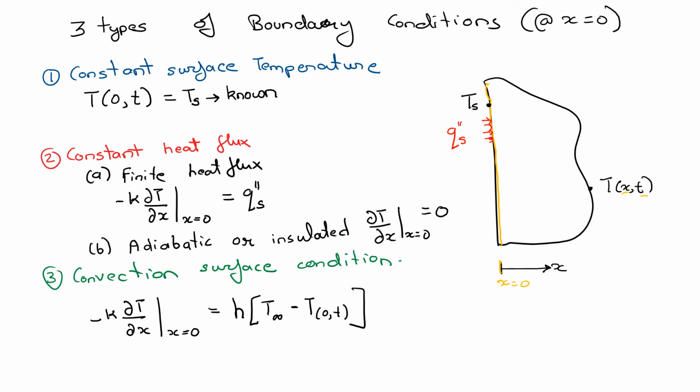In this case, your surface is convecting with some fluid which is at a temperature T infinity and has a heat transfer coefficient of h, and that will be the boundary condition that you will use.